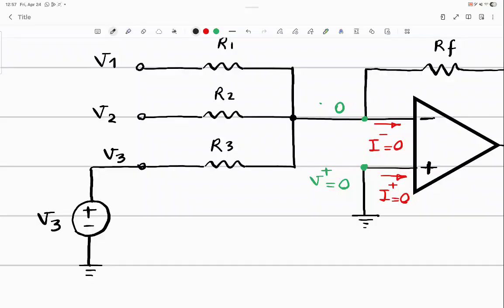When I write V1 beside that, it means that there is some circuitry before that that is forcing that point to have a voltage of V1. We don't know how, we don't care. The only thing is that that voltage is V1 and the current is not 0 necessarily. Okay, it's not open. It may seem open, but it's not. Okay? Am I making sense to everyone?